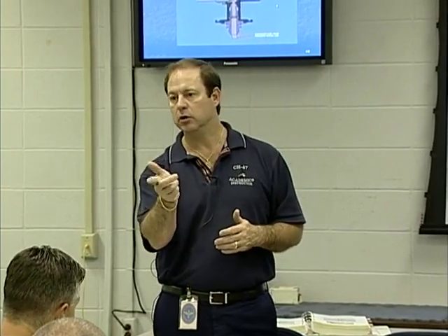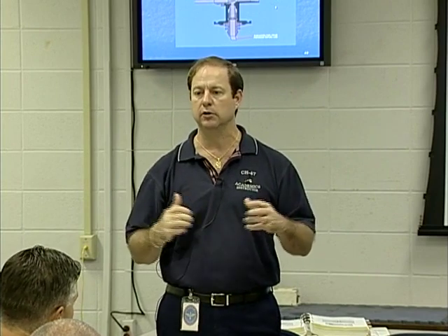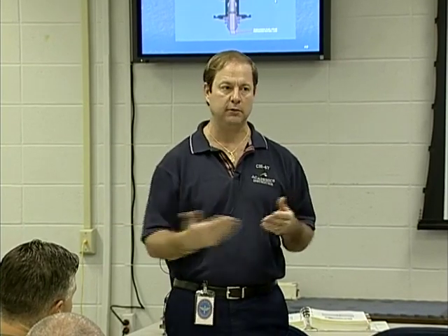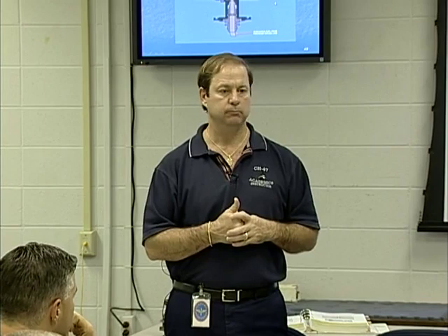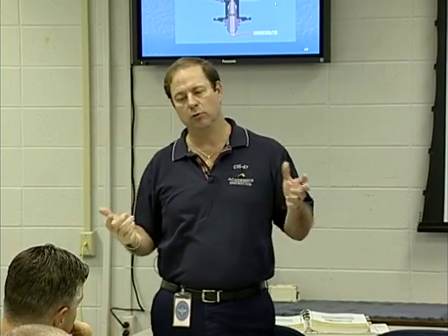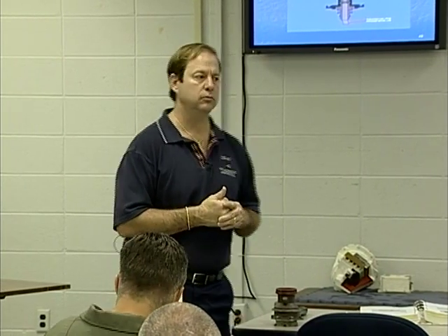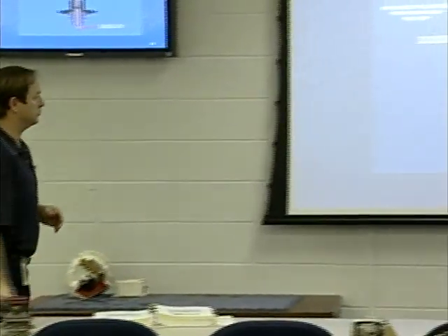Now here at Mother Rucker, you may not see that process because the POL handlers actually do that for us. The crew members don't stick around and wait for the fuel truck to come, so they do that automatically. So what do they do, crank the APU and run those fuel pumps? Yes, sir. We'll crank the APU up, APU generator on. They only need to run one pump, but it's faster if you use both sides. Any other questions? Good questions. Good job.